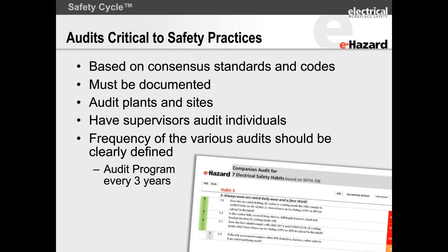And what we found out was there was a metal contamination, which is very, very unusual. Don't get scared that your uniforms are failing, but it was a very unusual high metal content workplace with metal dust, and it was getting into the garments and not getting out satisfactorily, and it was blocking the flame resistance of that particular garment. And they were able to solve that problem, but it was a real problem.